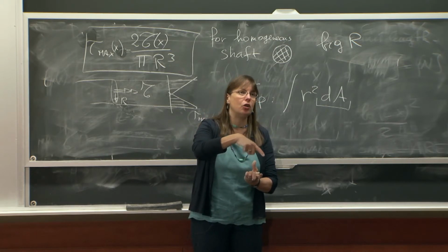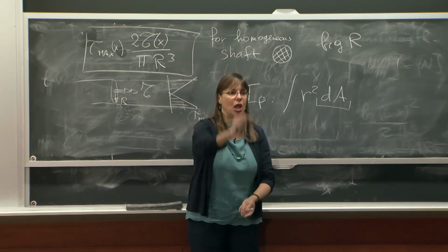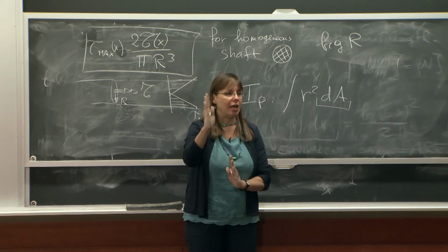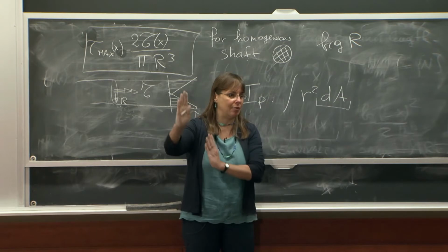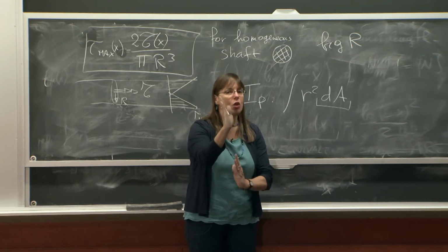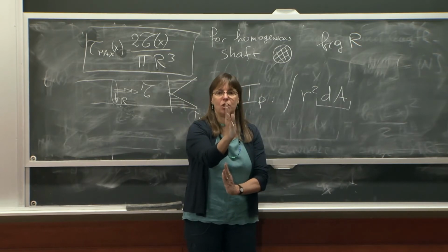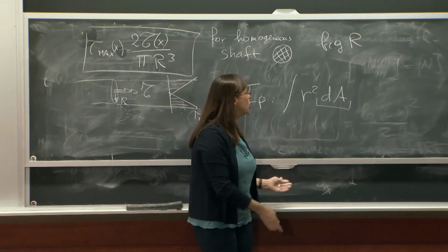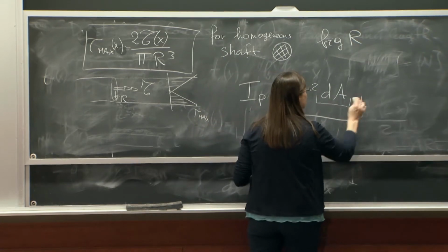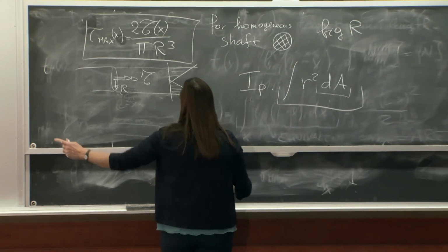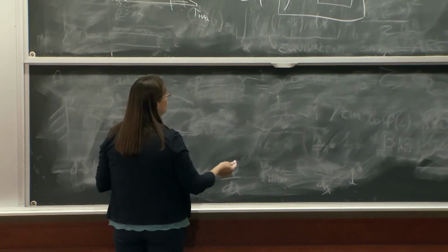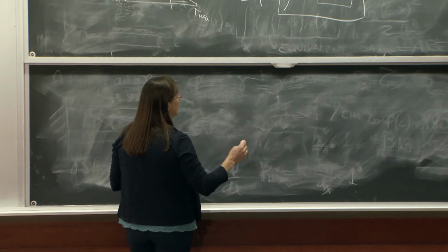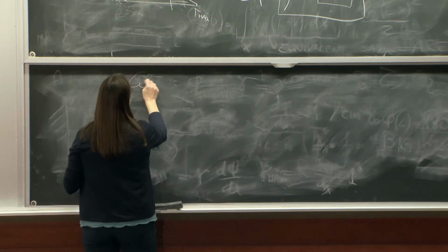It's not like axial loading, where I could make it into the shape of a butterfly, and it would carry the load the same as a heart shape or a circle would. It wouldn't care what the shape of the cross-section is. When I work with torsion, because I have this part here that matters in the stress, I can play games with that.